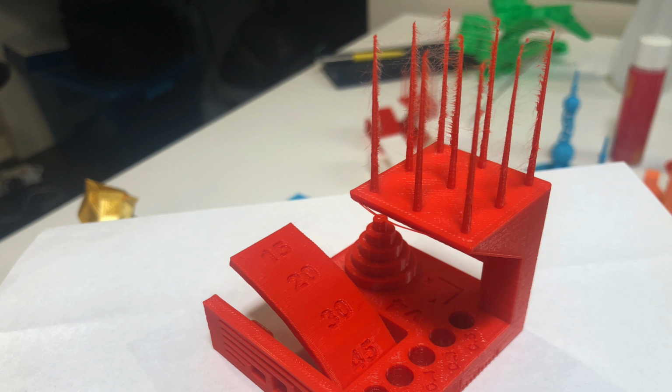That takes time to pull the filament back. When you're pulling it back from a Bowden tube, you have to pull it back more to be successful to get clean prints. So Bowden tube-based printers are inherently slower.